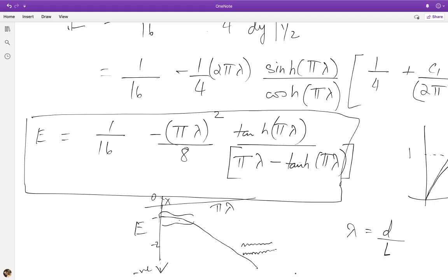The basic idea being that if you see a problem that looks complicated in the sense that the boundaries are complicated, the question you should ask yourself is, can you solve this problem approximately by writing it as a perturbation about a simpler problem on a simpler domain? So the same question is what you ask yourself in other perturbation problems as well, except there the simplicity comes from a change in the domain equations. Here we are looking to solve this as a perturbation about a simpler problem where the domain is what becomes simple. So in this case, we recognize that we could get an approximate solution and understand at least the behavior, for example, how the flow rate varies for flow in a wavy channel by solving it as an approximation about flow in a flat channel, provided of course the amplitude of waviness is small.